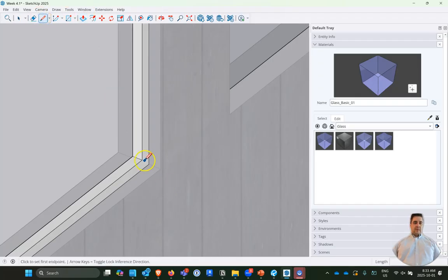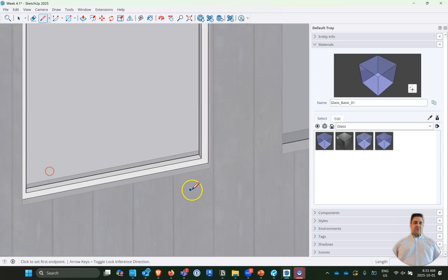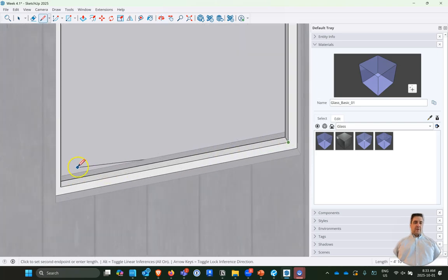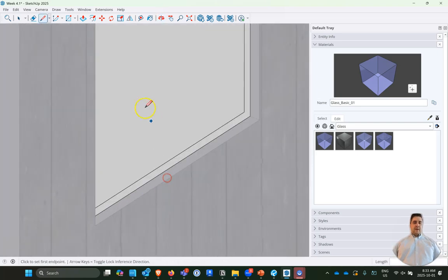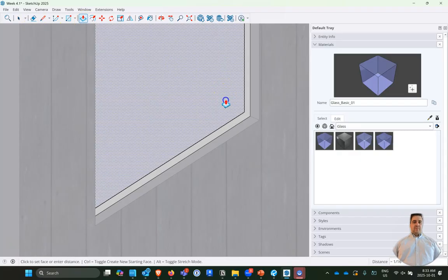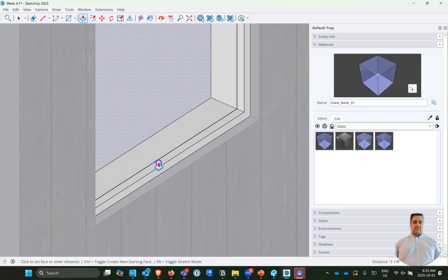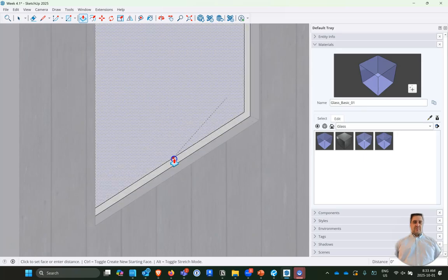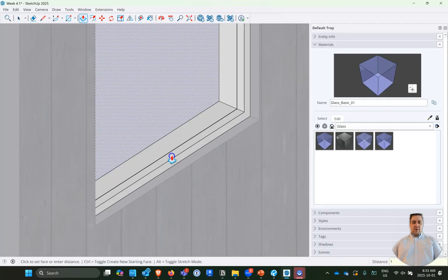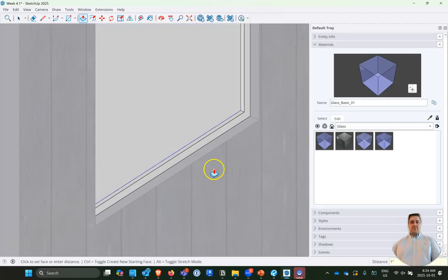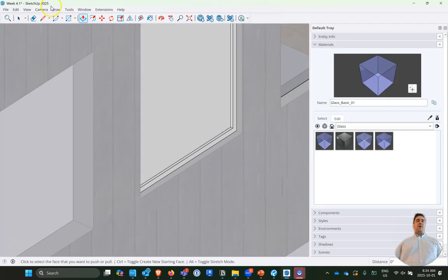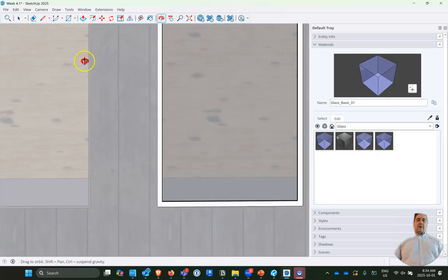And another way to do it is I can actually just draw one line on here, and I'm just going to extrude this in to the center of that object. If it lets me. No, okay, let's just extrude it in 1 inch, because we know it's 2 inches. And so now we have a few different places we can apply materials on, but by having that frame, it starts to look a little bit more intricate.